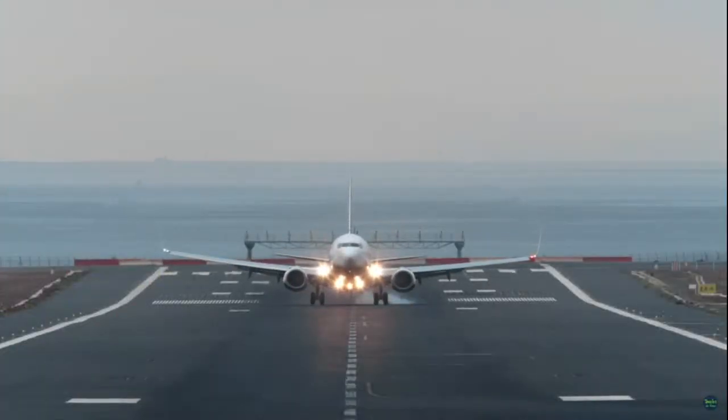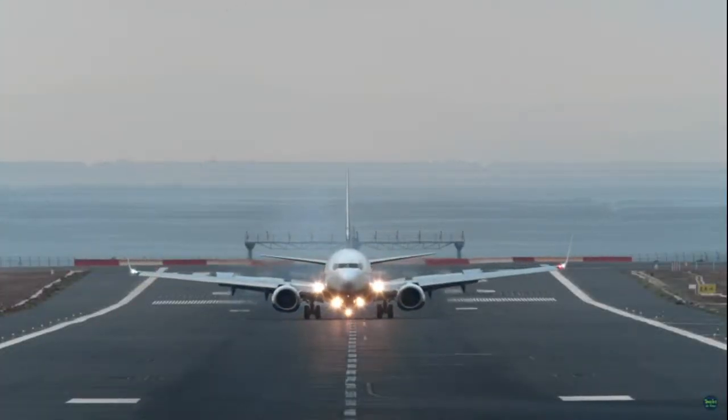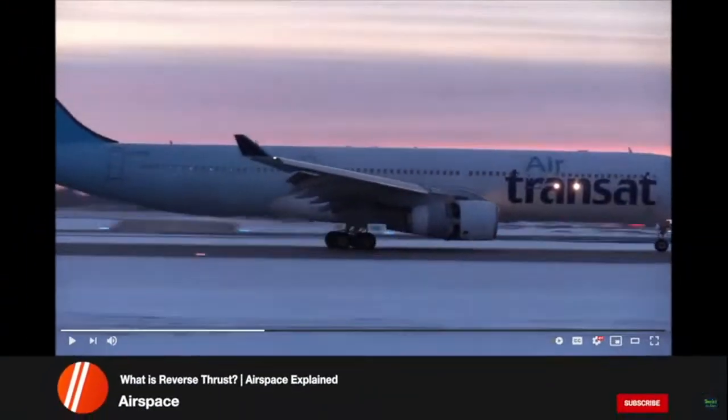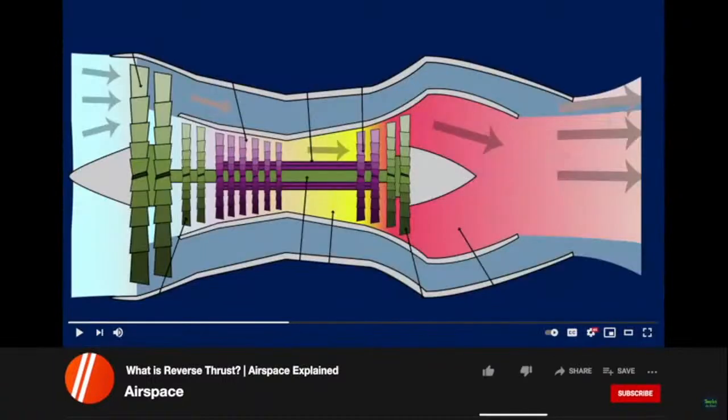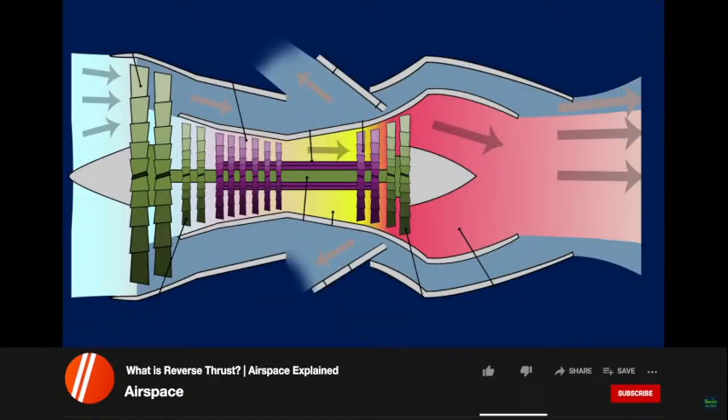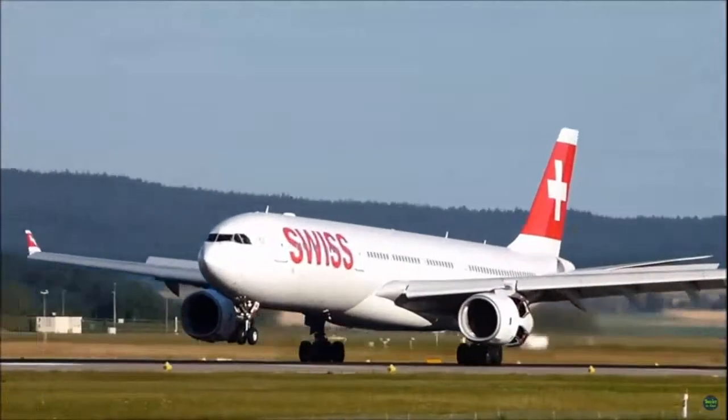Thrust reversers are the next one. Again, you want to deploy thrust reversers after you touch down, and the thrust reverser is an ingenious way of taking the engine's output, and instead of having to shoot right out the back, right, you take the inlet, goes to the compressor, and then it gets shot out the back. Instead, you have a door that opens, and instead of the air going right through, the air hits this ram and shoots back in the same direction, slowing you down. Now, in this situation, it looked like one thrust reverser was open, but not both, but that is another weird situation that's hard to explain. But those are the means that you have to slow down, and a lot of that wasn't fully handled.